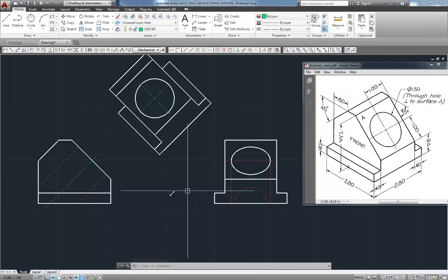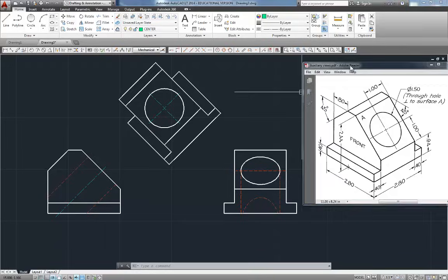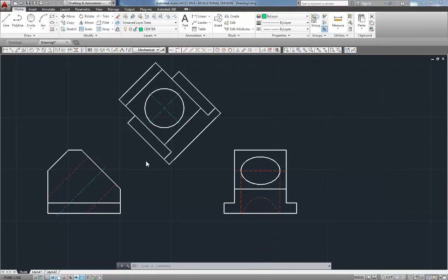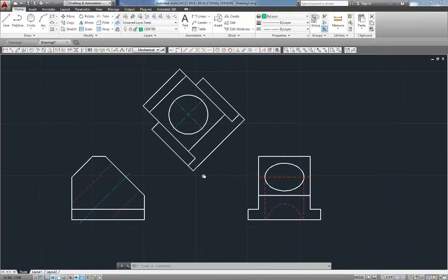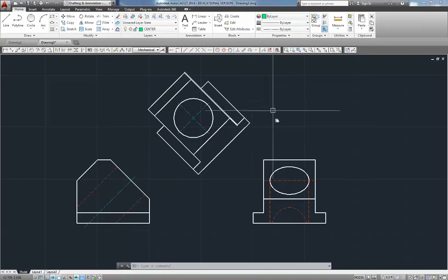Okay? And in fact, this would be our finished 3-view drawing. Get that out of the way. Our finished 3-view drawing for this particular auxiliary view would look just like this. Okay? So that's auxiliary view drawing. Again, utilize the UCS enter object feature to project your auxiliary view. Check your view spacing on your handouts.